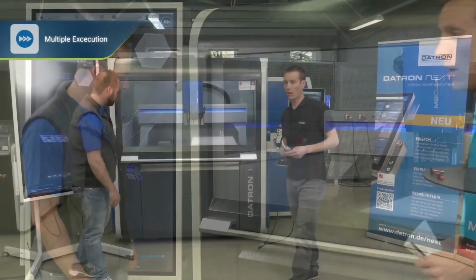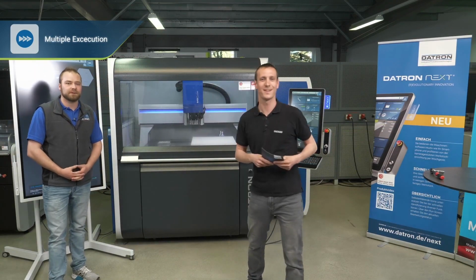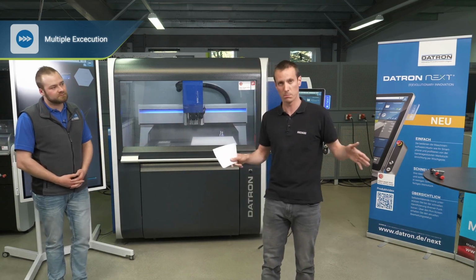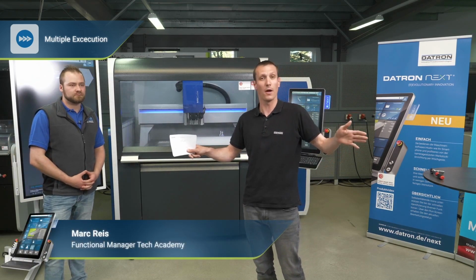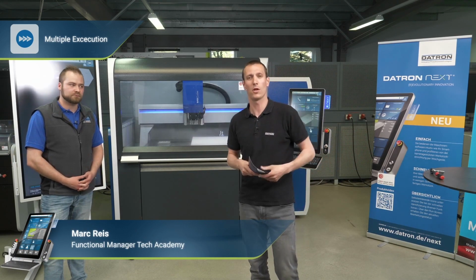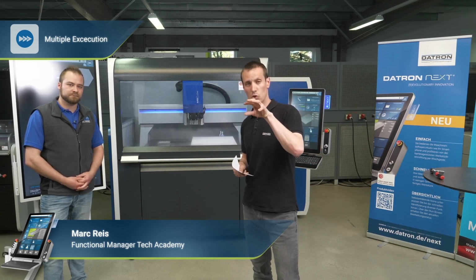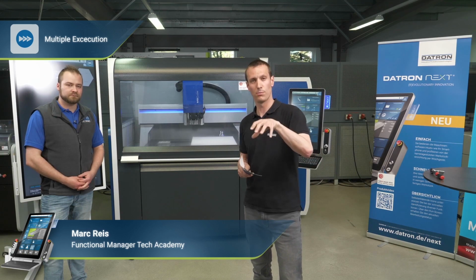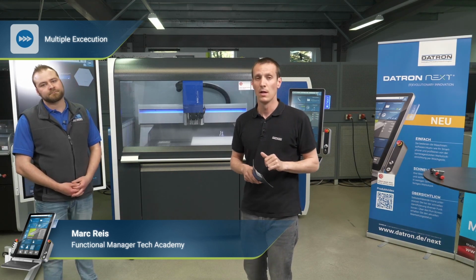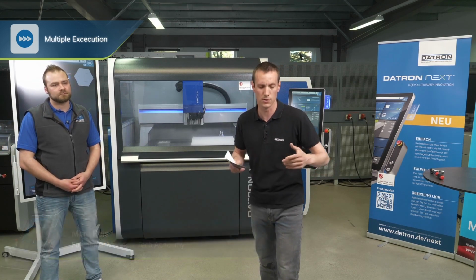Right, and speaking about the multiple execution, if you have a big sheet and you want to get most parts out of it, let's say you cut 100 small parts out of a big sheet, 1 meter by 700, you can do a lot of parts at a time. You want to make sure that tool wear and tool breakage is observed, that the machine has an eye on this. And that's why we have the so-called sister tool option.